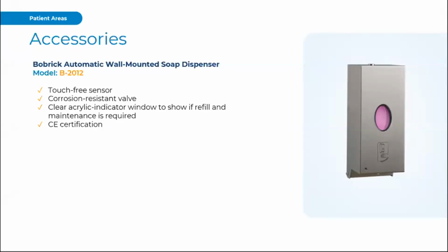So for OBC, a soap dispenser must operate automatically or is operable using a closed fist, with a force not more than 22.2 newtons or 5 pounds. That Newton line is going to come up regularly across multiple fixture categories. There's location details as well, not more than 1100 millimeters above the finished floor and within 500 millimeters from the front of the lavatory.